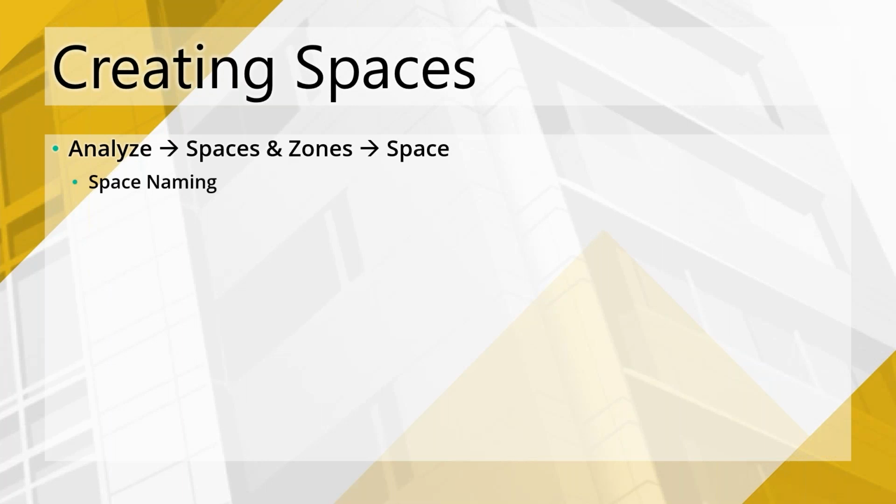Before we do the space naming, though, one of the things that I like to do is delete the unnecessary spaces, because I'm going to be using a place automatically option for each of my levels to save me a bunch of time. And when you do that step, you end up getting a lot of extra spaces that aren't necessarily valid, and we need to find a way to quickly delete them. I'm going to be building a temporary schedule in Revit to help me do this and show you some techniques that I leverage to very quickly strip out the junk, the stuff that's not really needed. And again, for that, I use a temporary schedule.